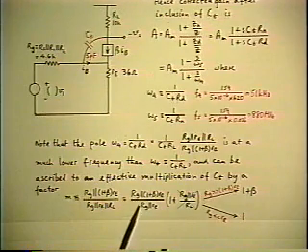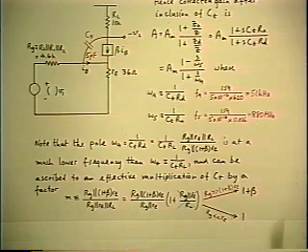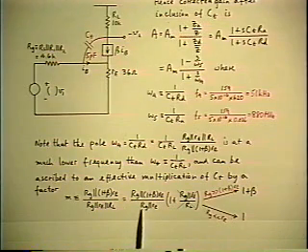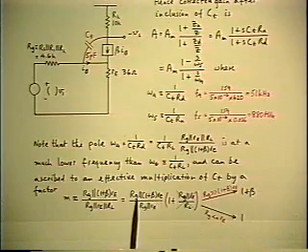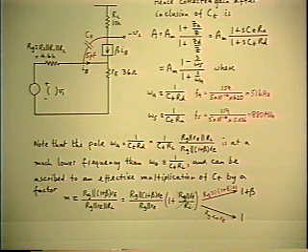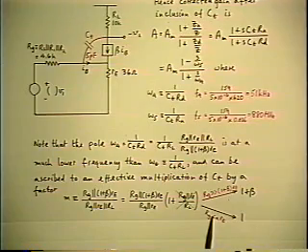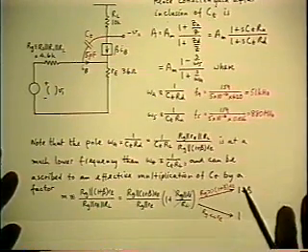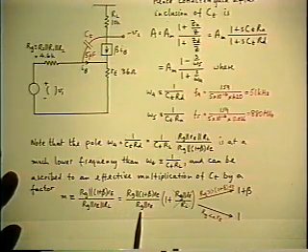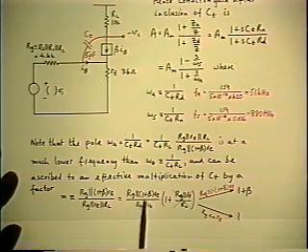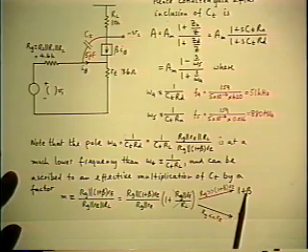In fact, you can easily see that it's a bilinear function of that resistance. Because if you multiply out the parallel terms, you end up basically with an RG plus something over an RG plus something else. That's a bilinear function. So it has two extreme values. And those two extremes are, if RG is very large, this ratio tends to 1 plus beta.